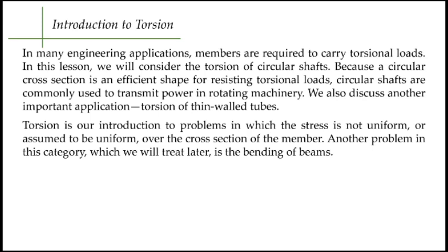Now, one thing we should also remember is the new knowledge that we're going to acquire from studying torsion. It's because torsion is an introduction to problems in which stress is not uniform or assumed to be uniform over the cross section of the member. Now, if you can remember the discussion we had in analysis of stress, normal stress is equal to the applied load normal to the cross-sectional area, right?